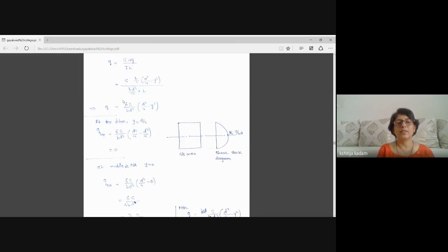Here you understand two, three things. The value of shear stress Q depends upon Y. And that means it is not constant across the thickness. Second thing, it depends upon Y square. That means the variation of shear stress across the thickness will be second degree, parabolic. Third thing you understand that we have to calculate the shear stress across the thickness one by one.